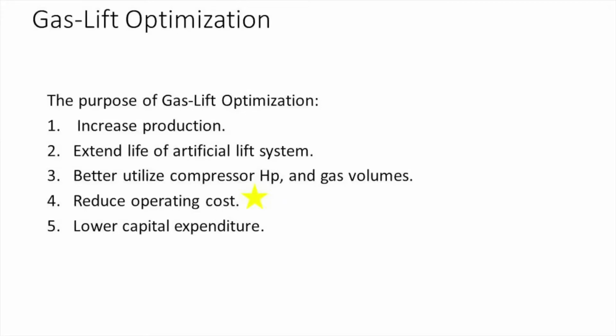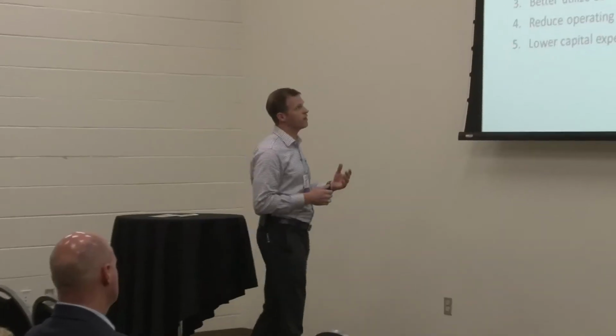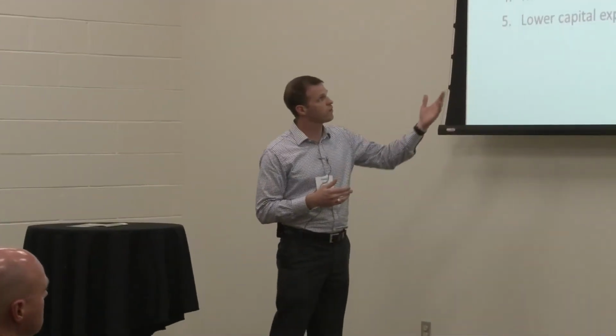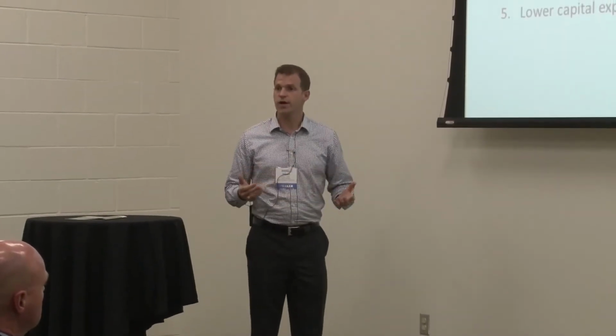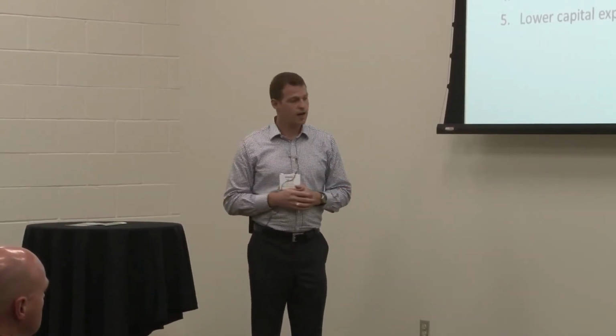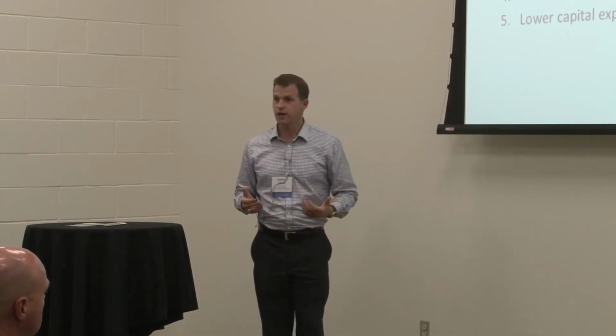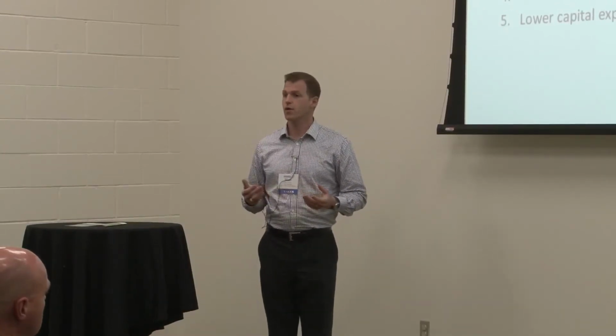Some of the purposes of optimizing gas lift: the biggest one, of course, is increased production. But a lot of times, especially in later life, very tight unconventional reservoirs, that increase in production is very minimal on a well-to-well basis. So we start looking at other things. The biggest one is utilizing compressor horsepower correctly. Most compressors used to supply the pressurized gas to gas lift wells are on a rental basis.